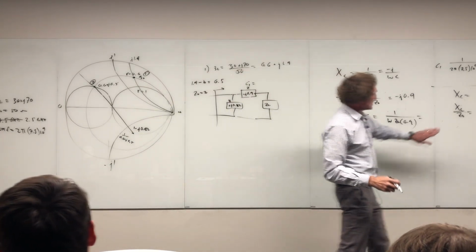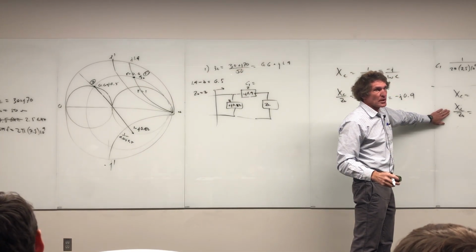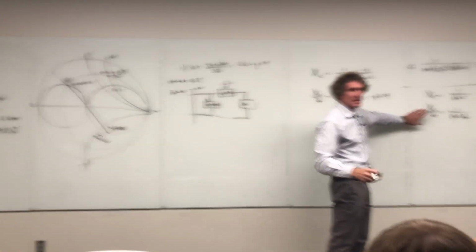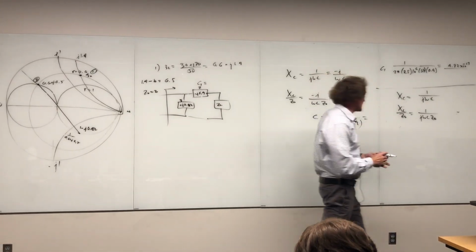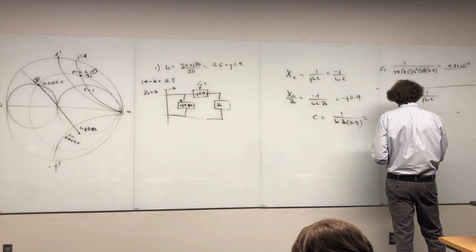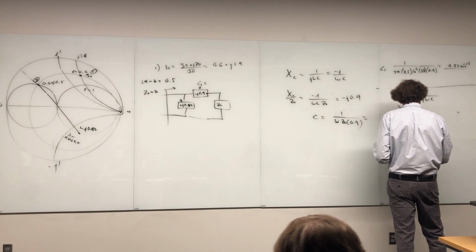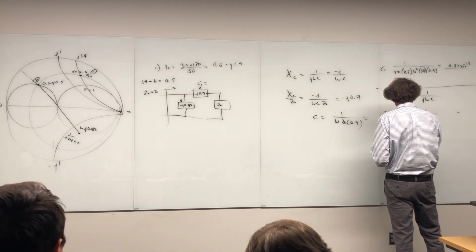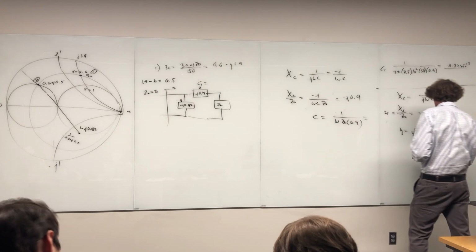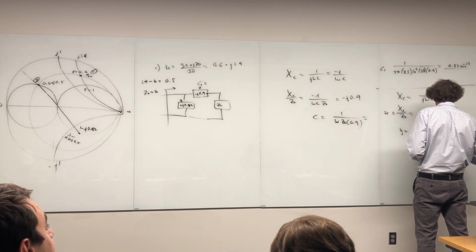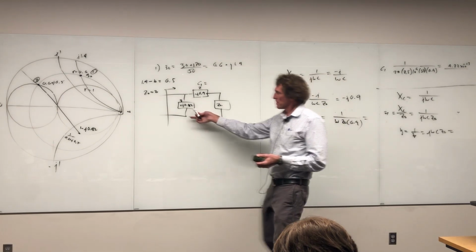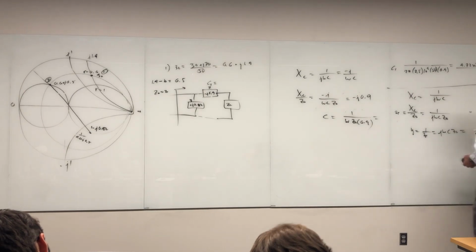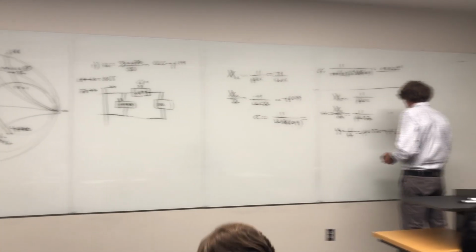All right, so this is normalized impedance, right? We don't want that. We want normalized admittance. We flip the whole thing, but it's normalized. I always normalize stuff in the impedance domain. Then I flip it. Now I'm in the admittance domain, and my normalized admittance is going to be equal to 1 over the normalized impedance. I'll call it 1 over ZP, and this is going to be just J omega C Z naught. And that's equal to this value right here, J 0.82. I'm putting in everything, so it's J 0.82.